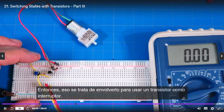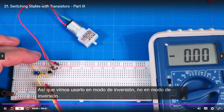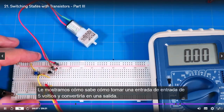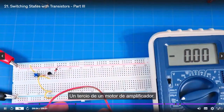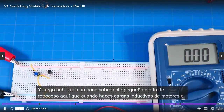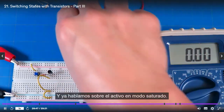All right, so that about wraps it up for using a transistor as a switch. We saw how to use it in inverting mode and non-inverting mode. We showed how to take a 5-volt input and turn it into an output. Then we showed how we could use this to control a large load, in this case a 1/3 of an amp motor. And then we talked about this little kickback diode, which, when you do motors and inductive loads, protects your circuitry.